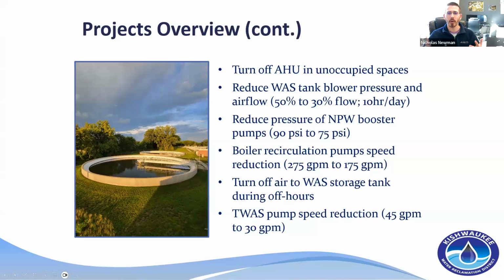I kind of want to just go over a couple other types of projects we've gotten involved in that kind of just cover all our bases. So one thing we eventually kind of had to shift gears on as far as standard operating procedure is just turning off air handling units in places that are either unoccupied or are not occupied very often. It's a waste of power, it's a waste of gas. There's not really a point in keeping that stuff running if there aren't people that need the comfort brought by heating and stuff like that.